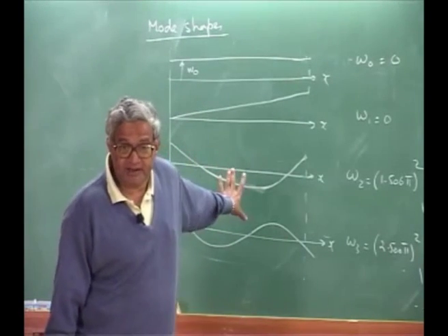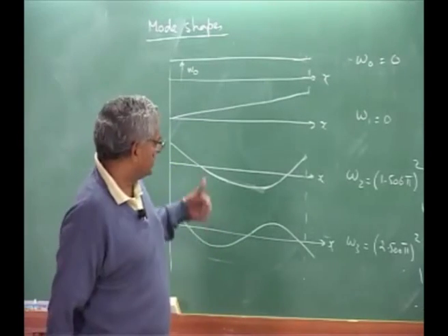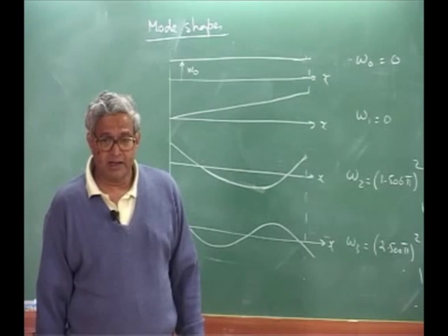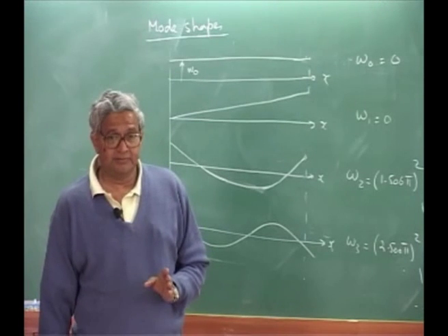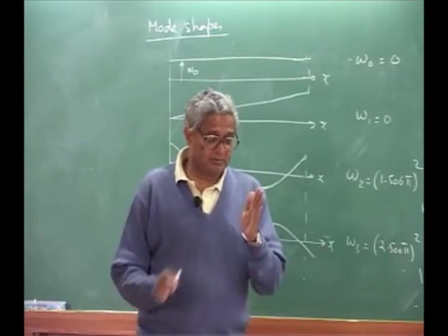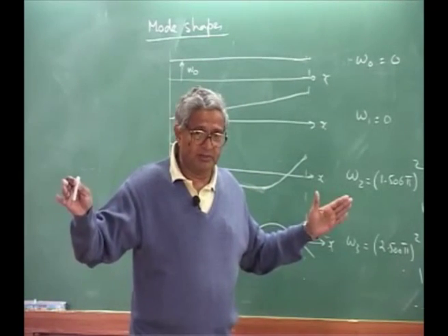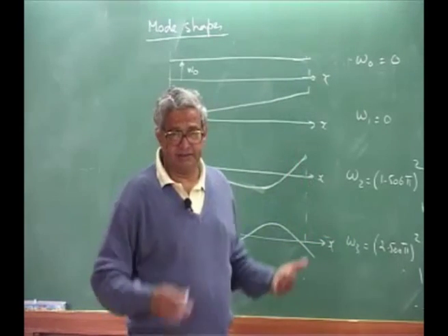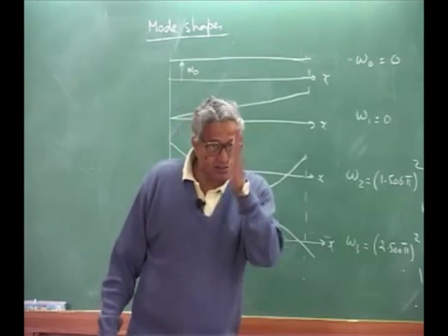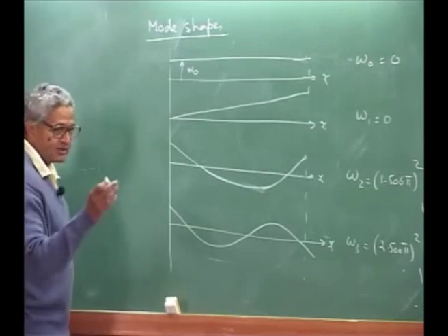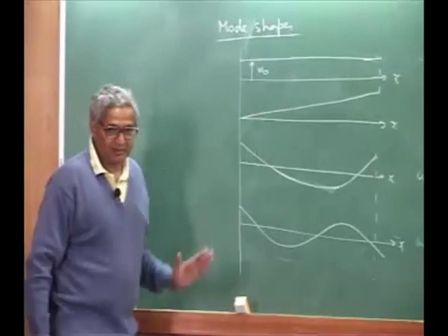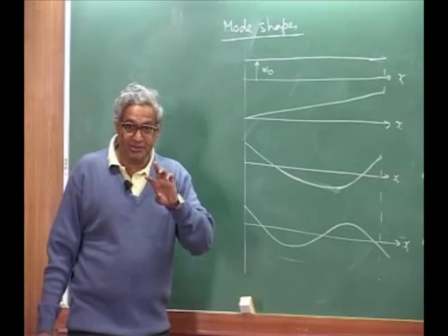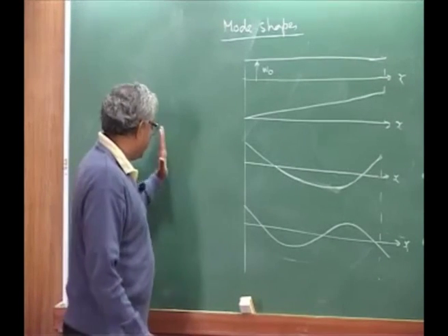But if you solve in this fashion, you will get exactly everything. Because symmetric mode, anti-symmetric mode, all the modes that are possible. Okay. On the other hand, that is why when you solve the full wing problem, it is better to solve both sides, if you are solving for an actual flight. Whereas if you restrict to half, you are saying, I restrict only 1/2 of the wing, then you need to be sure what boundary condition you set in at the midpoint.